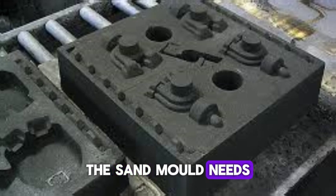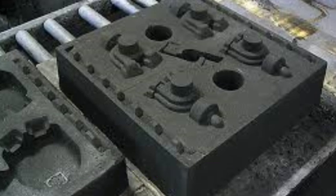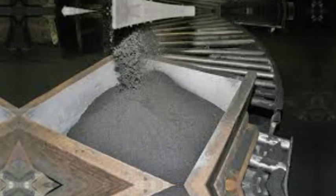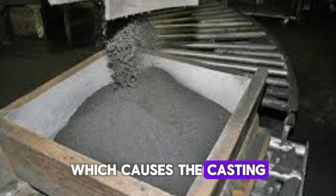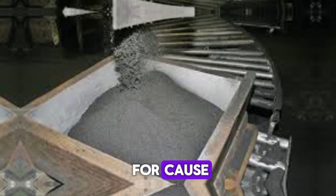3. Collapsibility. The sand mold needs to be collapsible once the molten metal inside solidifies. This will allow the metal to contract freely and naturally prevent the contracting metal from tearing or cracking. If the sand does not have the collapsibility quality, the mold prevents the metal from contracting, which causes the casting to break and split. This characteristic is crucial for cores.